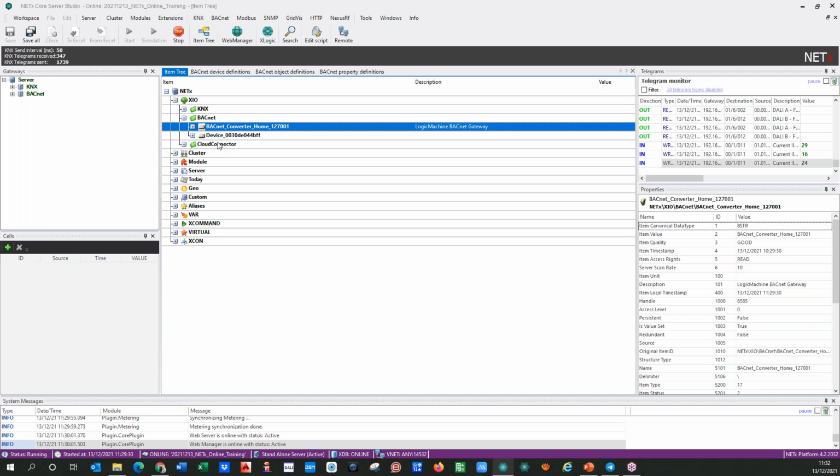But sometimes we have a specific SCADA or visualization that is a BACnet client, because the customer needs to integrate KNX or DALI or whatever, and Fidelio or whatever, in a BACnet specific visualization. And this BACnet client is from a third-party vendor, a different manufacturer, and they need everything in BACnet. This is not a problem for us. We can do it, but this will be explained in next sessions.